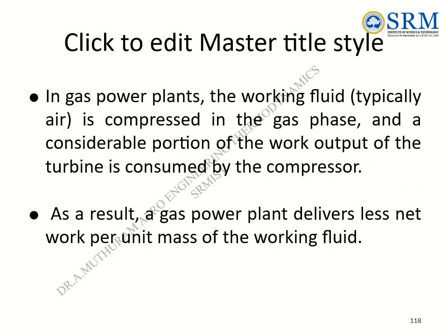In gas power plants, the working fluid, typically air, is compressed in the gas phase, and a considerable portion of the work output of the turbine is consumed by the compressor. As a result, a gas power plant delivers less net work per unit mass of the working fluid.